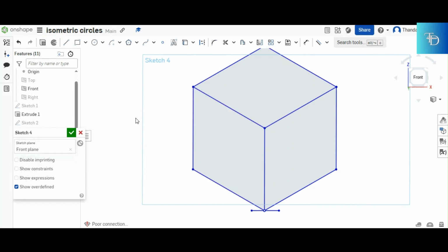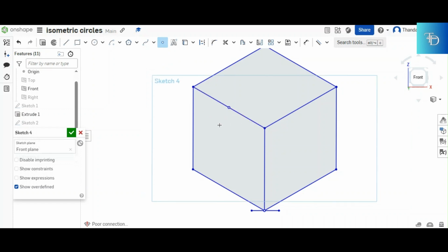The first thing that you do before you create that square, you should mark the center points of these 4 lines, because we are dealing with this face right here, which means we're going to have to get the center point there. We're going to have to get another center point there. You mark 2 center points and you transfer. By that I mean you're gonna have to mark 50, because from that point to that point is 100 millimeters. You're gonna have to mark 50. So you go over and mark your center point at 50, and then you're gonna go to the other side, or this side. You mark 50 right there, and then the next step that you do, you draw your center lines.